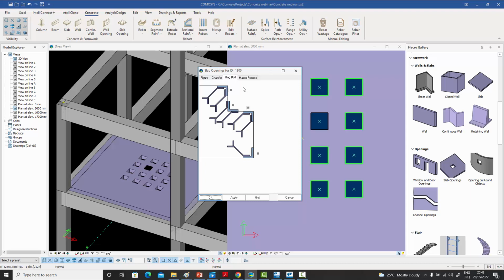Because if you don't do this modeling, what will happen is that your 2D drawings will be incomplete. And once they're incomplete, you will have to finish them off in AutoCAD. And once you start doing that, there are revisions and more revisions and more revisions. So eventually, your model gets severed off from your drawings completely. So the idea behind 3D modeling is that you should model everything in the 3D model, not just half the building or part of the building. Because the moment you start modeling a part of the building, it comes back to haunt you, and eventually your model will be broken from your drawings, and that'll be the end of it.